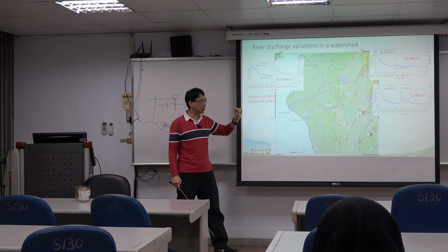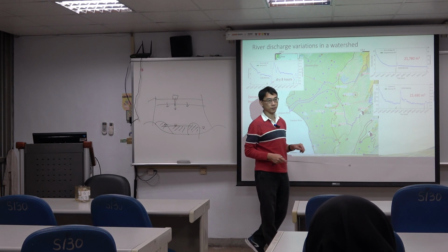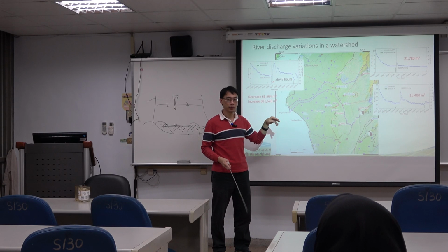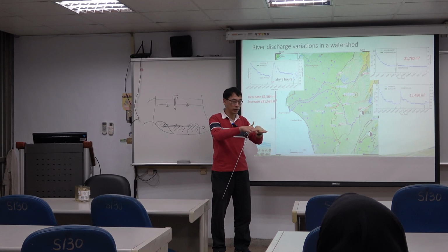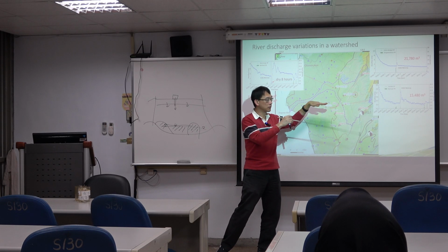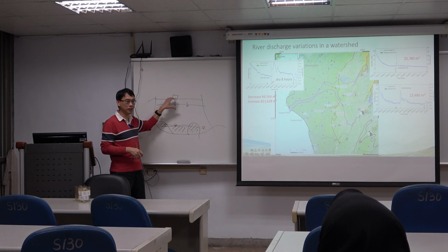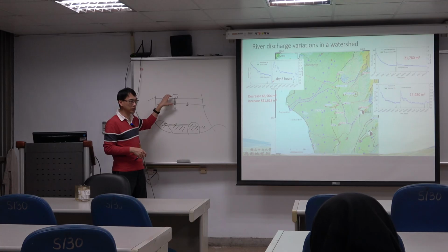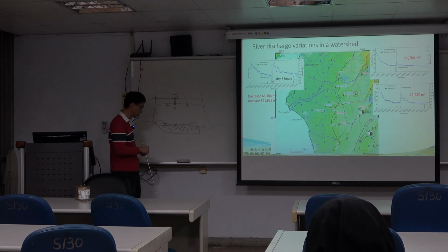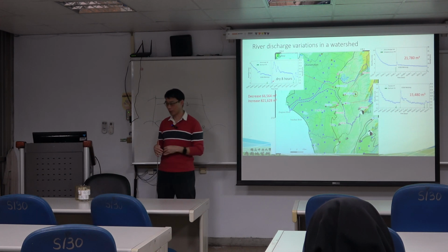But one possibility you can look at is whether the level goes back to the original level or not. If it goes back, maybe the data is still reliable, because that means it was just a disturbance that let the water uplift and then it went back. But if you see permanent changes, it might imply that your bridge or your system was disturbed. Okay, so the data might not be totally correct. Always remember, when you gather data, be careful about the data quality.